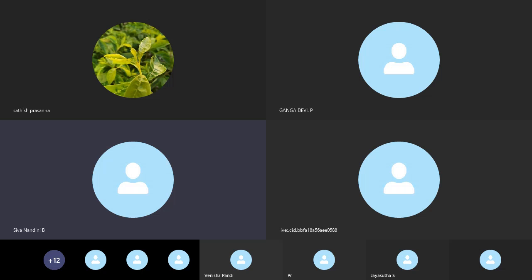The table below shows the frequency and skin depth. We have already said this PCB is meant for high frequency and low cost applications. For different frequencies, what are the values of skin depth? That is, the copper depth to be coated over the board is provided. The skin depth is provided in terms of millimeter as well as micrometer.